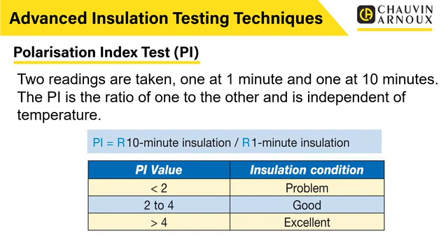This gives us excellent time for that insulation polarization to take place, and for us to get a key idea of what's going on. So sometimes, like we said, for higher test voltages or for bigger installations, this may be a good idea to try. Again, you can do both. You could try a DAR test, and if you're not 100% convinced with that, go for a polarization index test. These aren't exclusive. You don't have to just pick one.